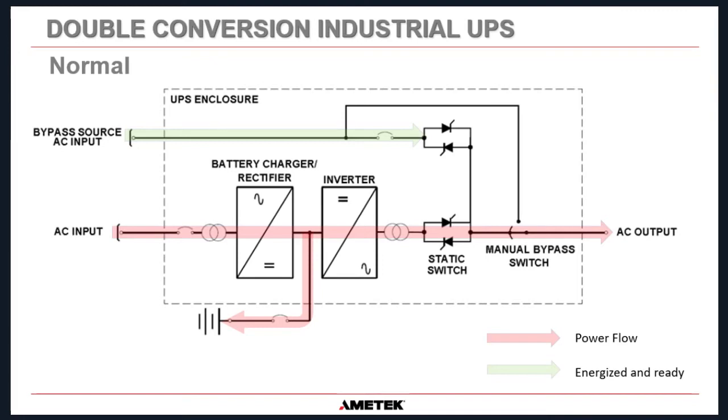That goes through a transformer, which then goes through the static switch. So you can see this static switch is in circuit all of the time. Power flows through the static switch, out through the manual bypass switch, which is in the normal position, out to the AC output circuits. So that is normal operation for an industrial UPS.